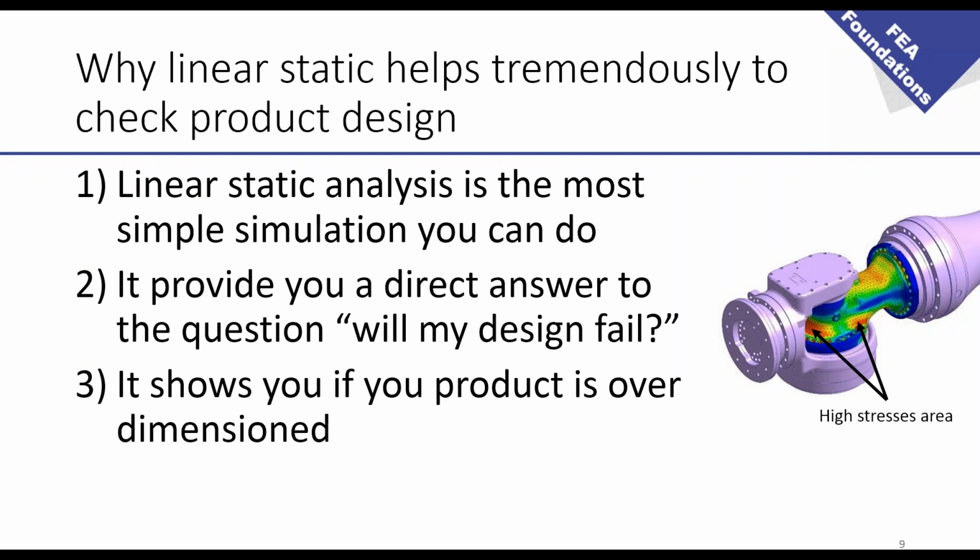So you have to know that because there's a lot more analysis types behind that you use in special cases, but linear static is really, let's say, the basis. If you say I'm doing finite element simulation most of the time, it means that you're doing linear static. So from what I know, like 90% of the analyses are done in linear static. So then why do we use linear static?